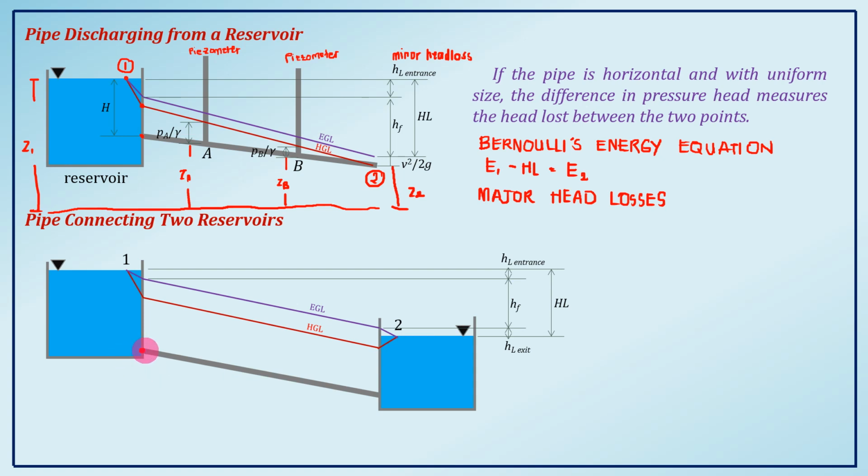Then, your liquid will travel from this point up to the point where it goes to reservoir 2. So, the travel of our liquid from this point, let's say point A to point B, has a certain drop on our EGL. So, there was a drop in the EGL and that is your head loss due to the friction at the wall of the pipelines and in the fluid.